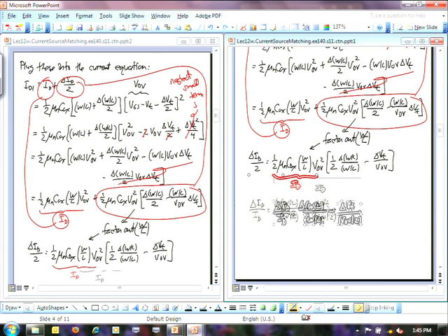Okay? Now, you may look at this. Okay, I need to address this, right? So this minus sign there, you're saying, okay, wait a minute. What are you talking about here? If I make my VOV smaller, doesn't that make this whole thing smaller? Because that's a minus sign after all, right? But in this kind of analysis, pluses and minuses mean nothing, okay? Because the worst case is that this delta VT is negative. So what you do is you take the worst case, right?